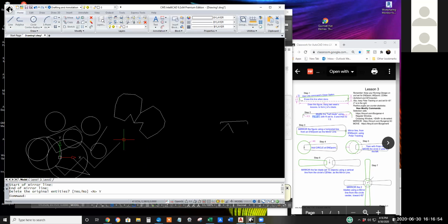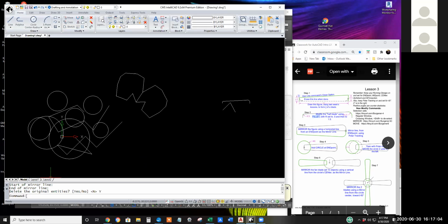Getting there. You said, well, nothing selected, you select mirror. Right. Nothing selected. The command area says command. Polar tracking is on and set. Object snap is on and set. I can't point to them because my Zoom stuff is covering it up. The only status bar buttons are polar tracking and object snap. They're on and colored yellow and they're set correctly.